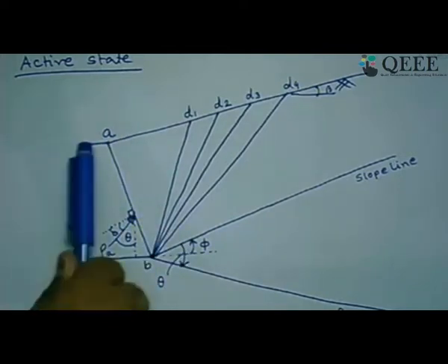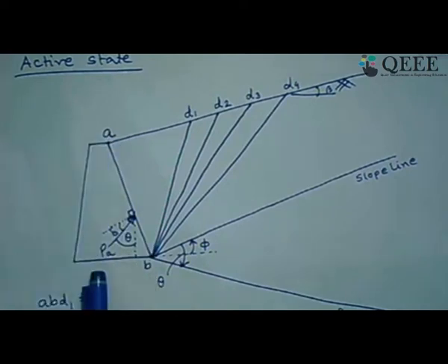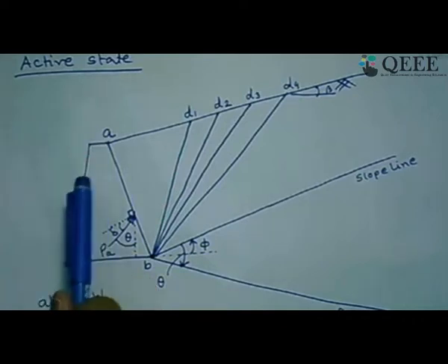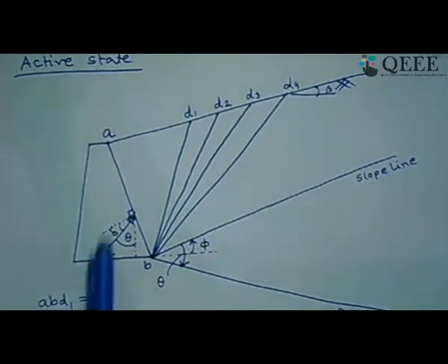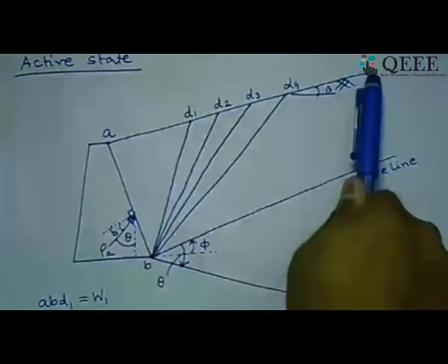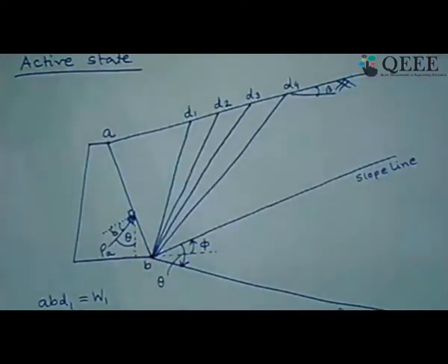That means in the space coordinate system, suppose it is 10 meters, we have to select a certain scale, let us say 1 centimeter equivalent to 1 meter, then 10 centimeters we have to draw, and accordingly this cross section and this angle also. So everything should be drawn to scale.